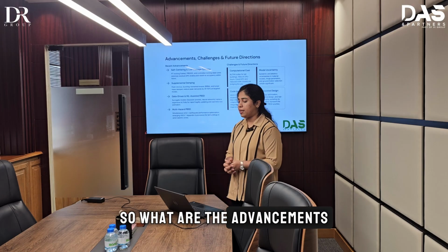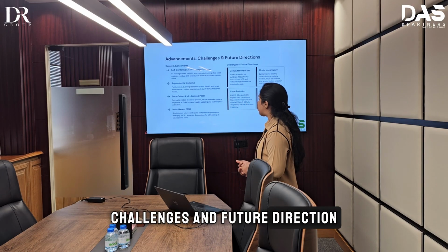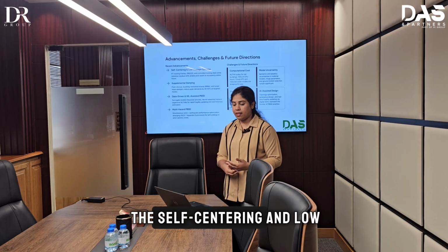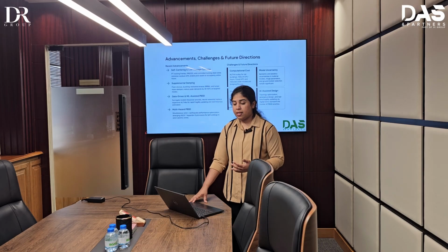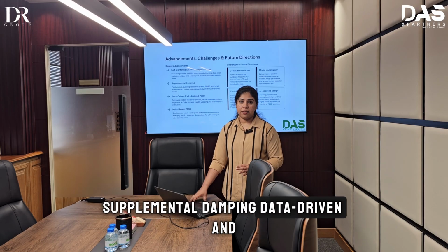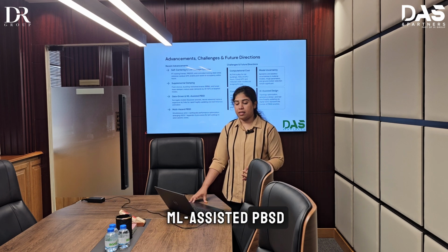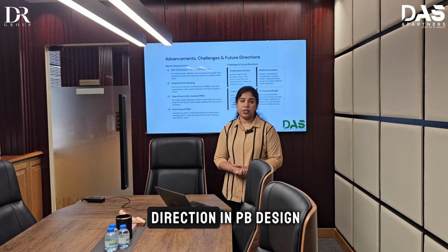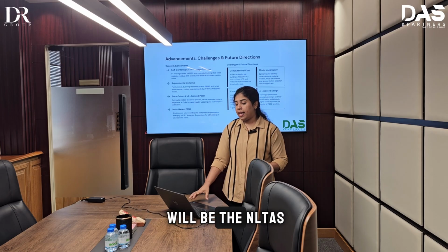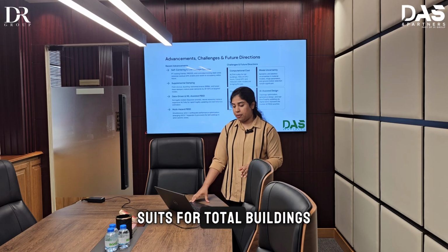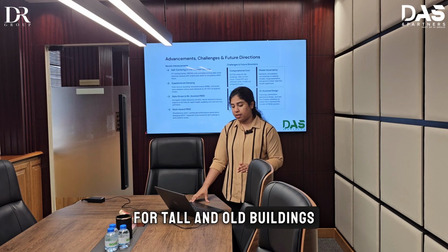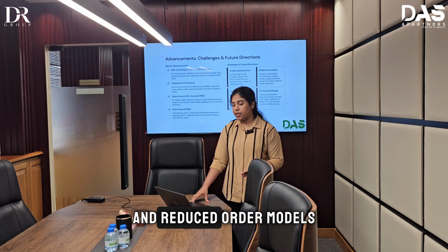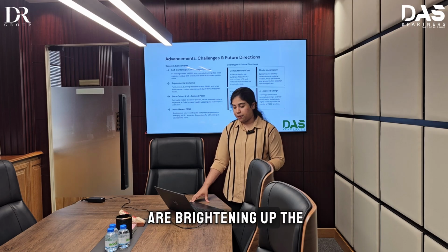So what are the advancements, challenges and future directions in this design category? The recent advancements are self-centering and low-damage systems, supplemental damping, data-driven and ML-assisted PBSD, and multi-hazard PBSD. The challenges and future direction in PB design: NLTHA suites for tall buildings take hundreds of CPU hours, so cloud HPC and reduced-order models are ramping up.